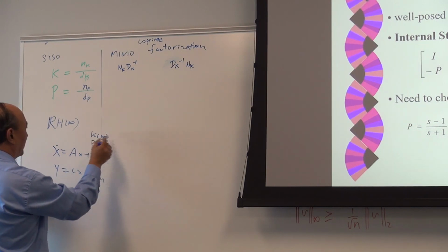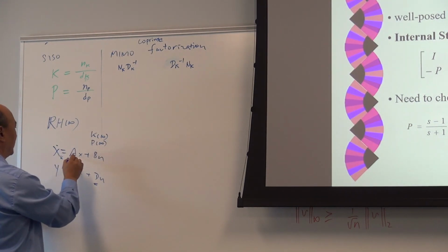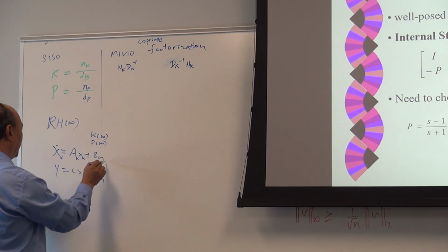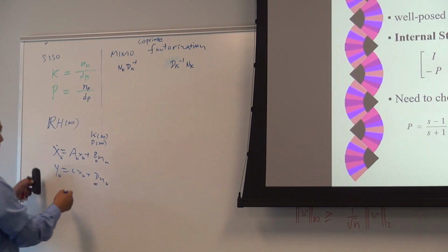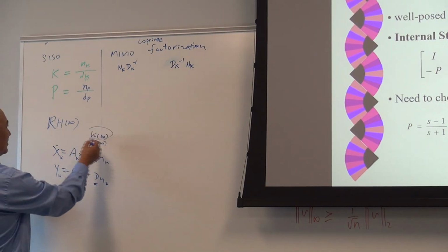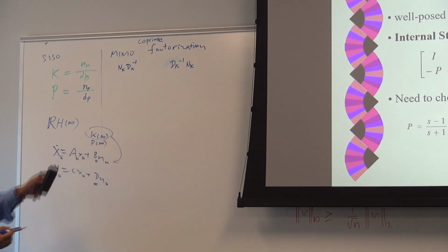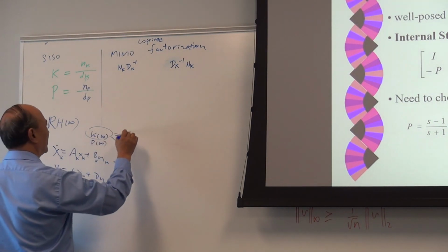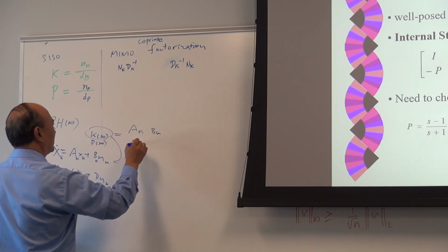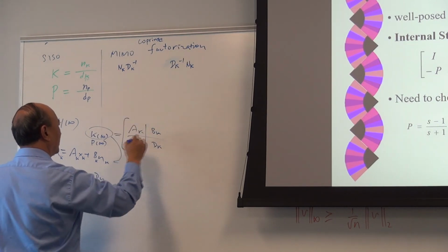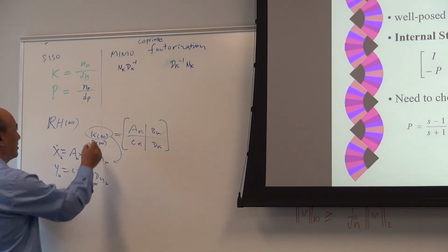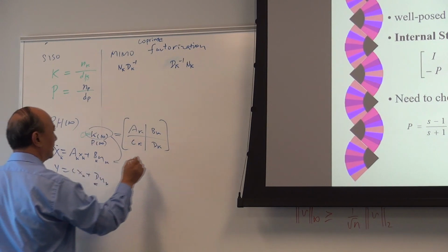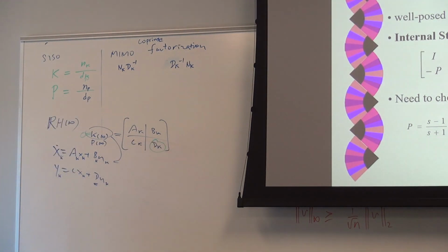So if you have a realization like xk, ak, bk, uk, so we don't want to write this messy form. I simply say this is ak, bk, and ck, dk, okay? So it's a state space realization. When we say this is 0, that means it's strictly proper.